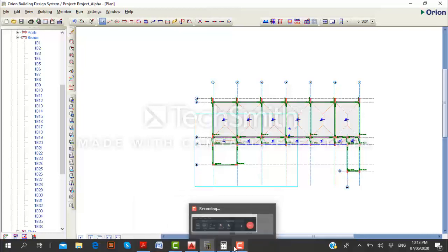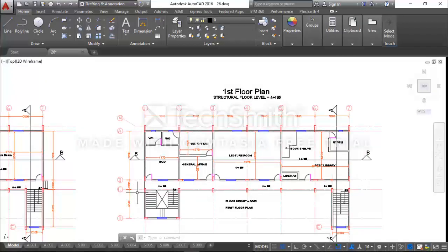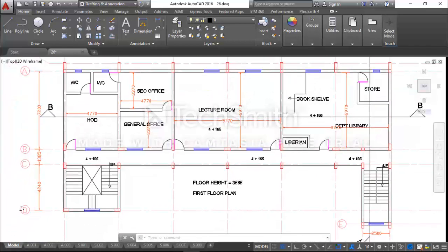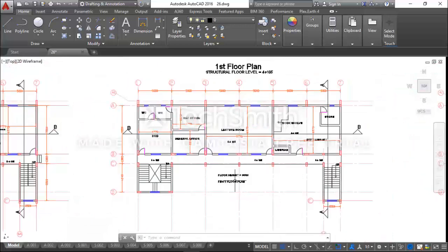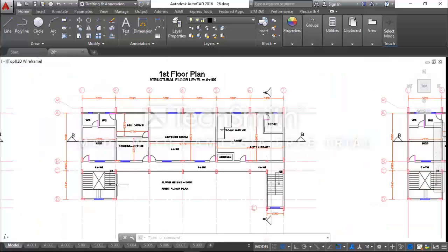I will check. Along the line C, we don't have any block wall there, but with small consideration, you will note that this is the first floor plan. You know that a railing, or a draft wall, will be provided here. It's not specified, but a draft wall of say 1 meter height will be specified between the line C1 to 6A.